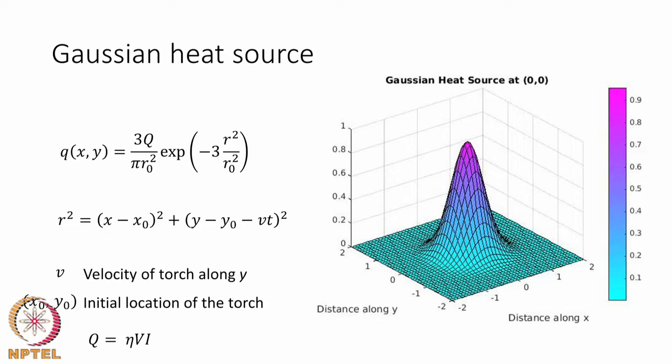So, you use the radius as a parameter r. So, you have e raised to the power of minus r square as a general nature by which the intensity is decreasing as you go away from the center of the heat source, and we have those numbers like 3 that are given to ensure that the variation is as sharp as what is normally seen in the actual arc,